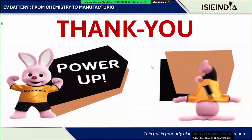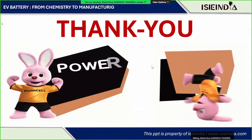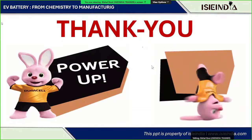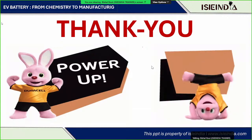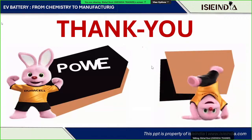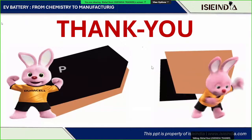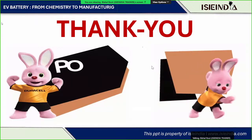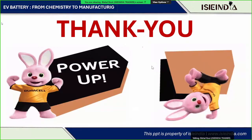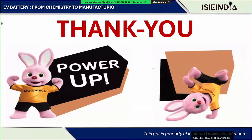They will perform a fire resistance and thermal propagation test. They will perform a water and dust resistance test, which is called an IP test. They will perform an overcharge protection test, where they overcharge your battery pack and see whether your BMS can protect it or not. They will perform over-discharge protection, over-current protection, and over-temperature protection tests as well. Then the short circuit protection test, which is a part of over-current protection, and for that you must connect a pyro fuse inside your modules. If you're utilizing a module-to-pack approach, you have to use a pyro fuse basically.